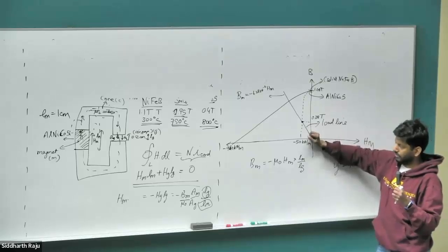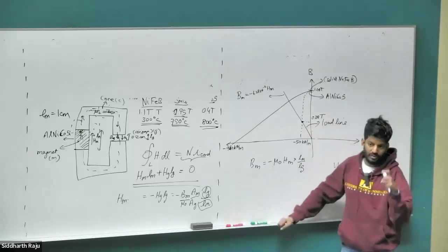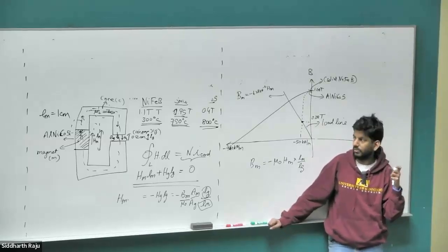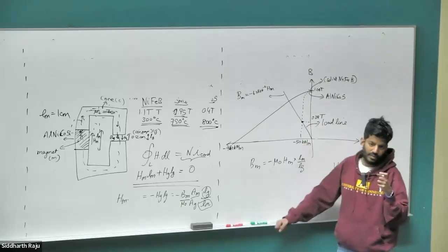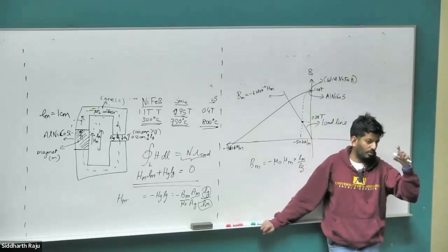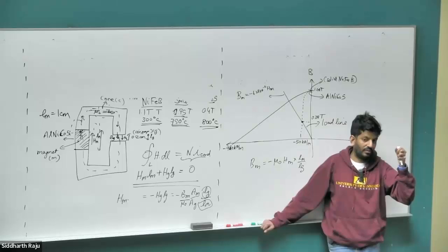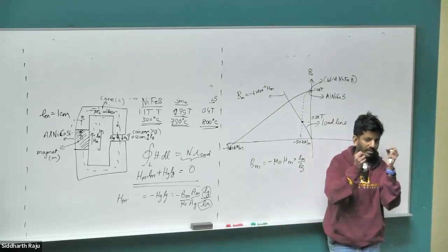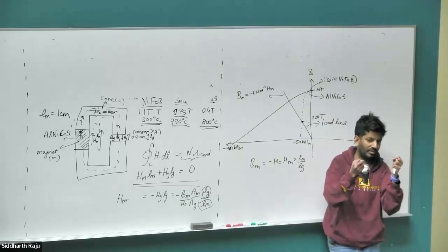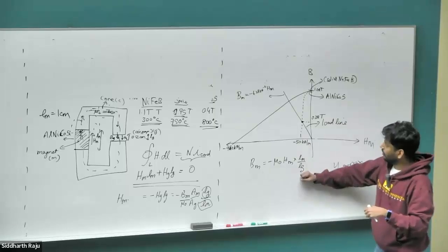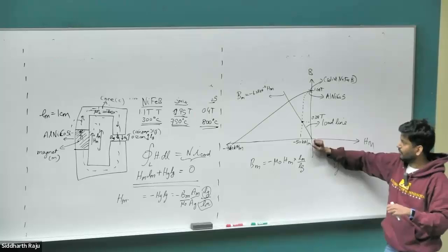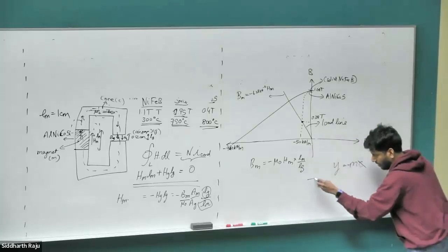You all would have witnessed this firsthand with those magnets that you get from state parks. Those are all Alnico magnets, because neodymium is quite expensive. When you stick these magnets onto your fridge, you'll know that they are stuck pretty tight. It's very hard to remove them. But the minute you remove them, even a slightest amount of air gap between the fridge and the magnet, it will feel as if you're holding paper. There is no force attracting it, because all it requires is a tiny air gap and the magnetic field plummets almost to zero.